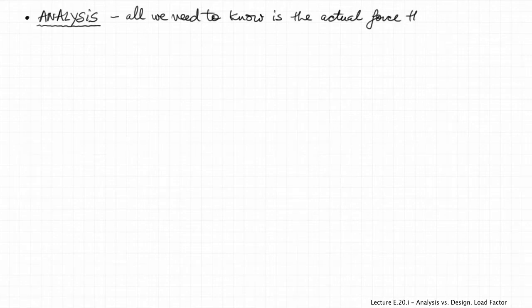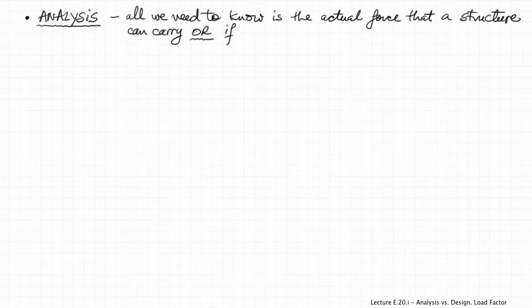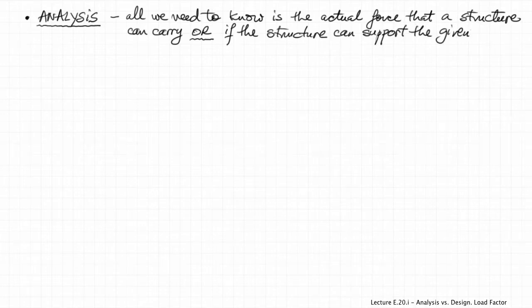By performing the analysis of a structure, all we need to know is the actual force that a structure can carry, or if the structure can support the given loads. So we need to know the exact number, the exact magnitude of the force, which, if exceeded, the structure would be in danger of collapsing. This doesn't include any additional safety factors.